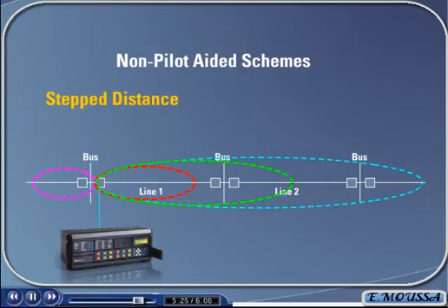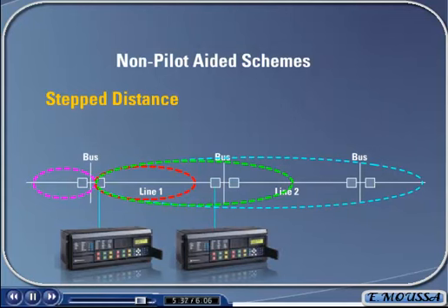However, the breaker on both ends of the transmission line must be opened to completely clear a fault. Therefore, another distance relay must be located on the right end of the transmission line to control that breaker. The relay on the right needs to be programmed with the same characteristics as the relay on the left. However, this one will be set up to be protecting in the opposite direction. Now, the zones of protection of each relay will detect any faults that occur on our protected transmission line.